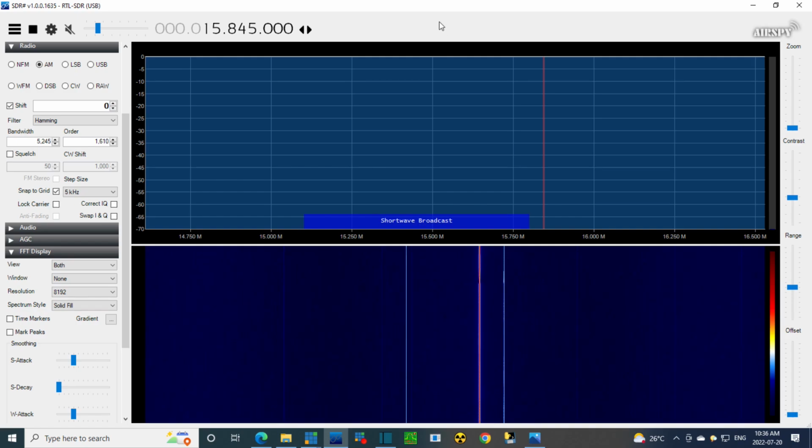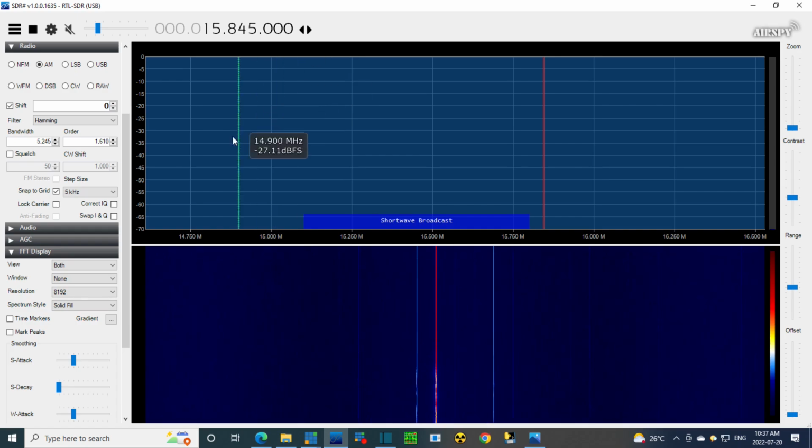Okay, I'm going to vary the tuning. There it is. It's red. Now I'll check to see if it's anywhere near the right frequency. In this case, I can tune this radio almost to 15 megahertz. So we're close to 15 megahertz here. So we should be close to 15,455. So there it is at 15,500, and it should really be 455. Should be over here, where this line is.